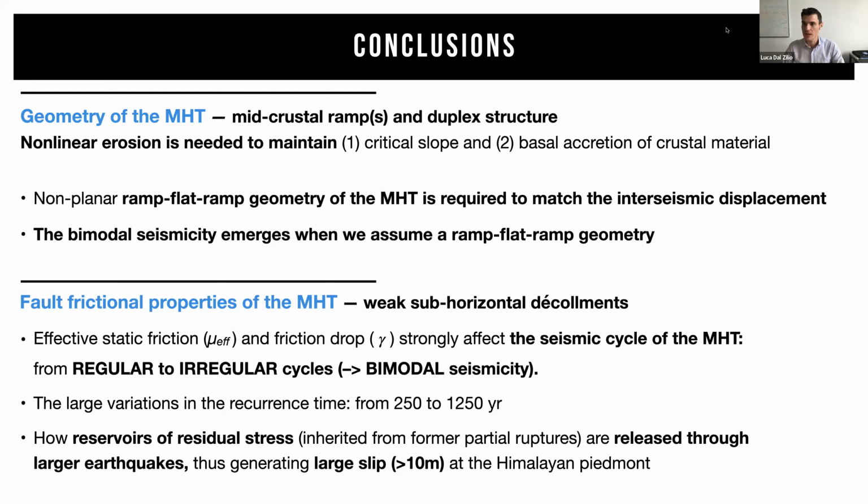I hope that in the future we can really work on improving the performance of these simulations, because it has started to become challenging, especially if you want to look at the future and really try to switch to 3D. But in order to simulate long and short time scales, we need a time step that adapts dynamically from very long ones to very, very small ones when we have a dynamic rupture and dynamic wave propagation. So we typically reach time steps of the order of 10^-3 or something like that.